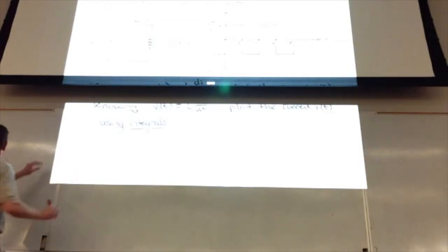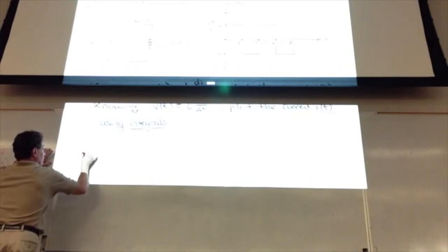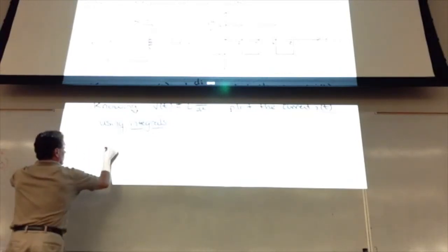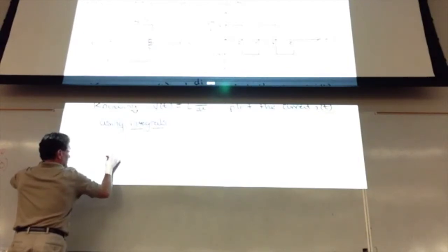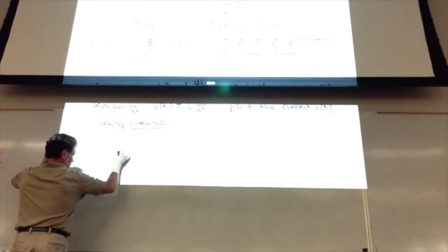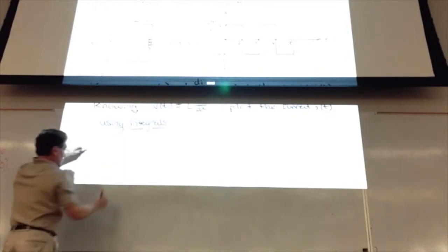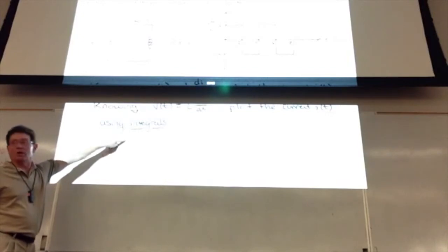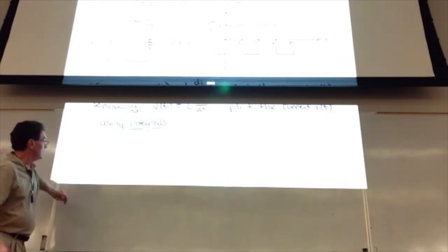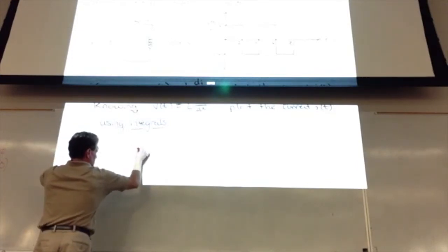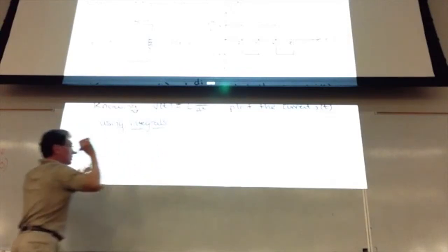All right, so now we put it in. I of t is equal to 1 over L, which is 1 over 500 times 10 to the minus 3, times the integral from 0 to t. I could make this 2 here, but I'm just going to make it t, and then substitute in t equals 2. This becomes the integral of plus 9 dt plus 0 due to the initial inductor current.